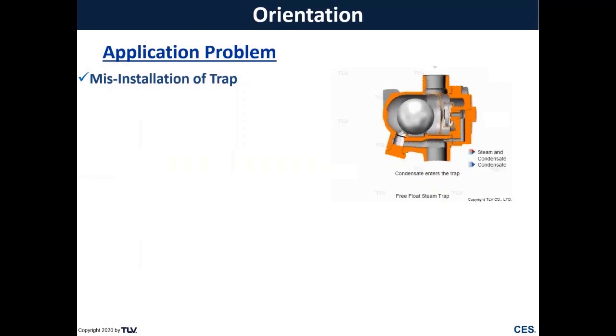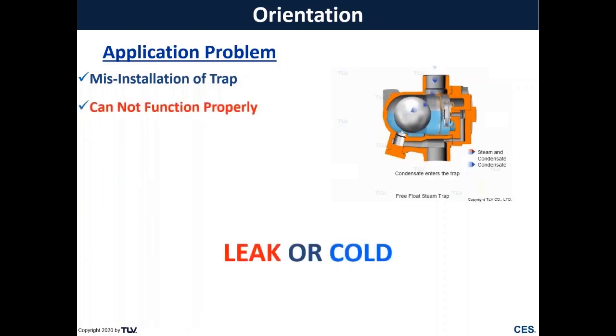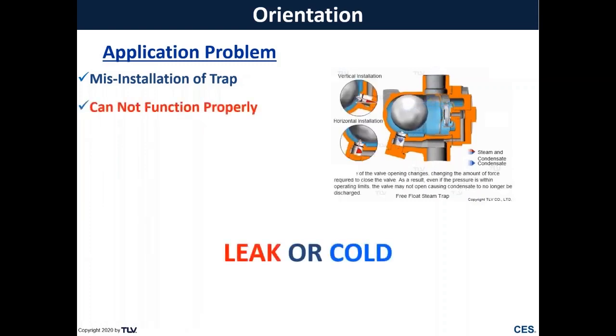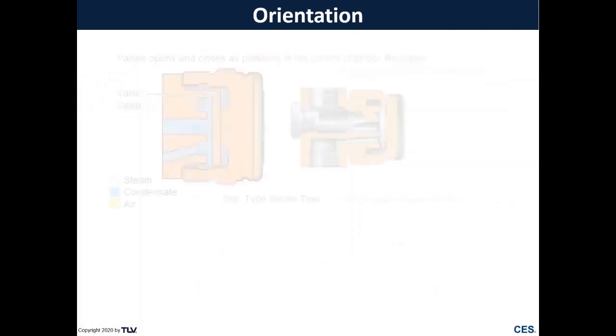So with this, it's really a misinstallation of the steam trap. So this could be a brand new steam trap, but it's never given the opportunity to function properly. And depending on the type of trap, it could leak or it could be cold if we have it installed improperly.